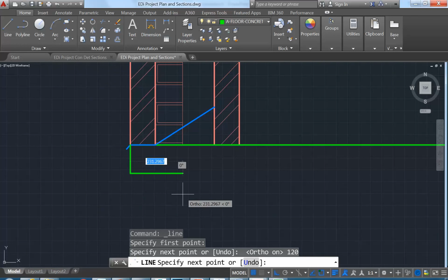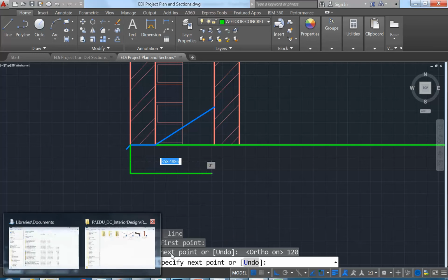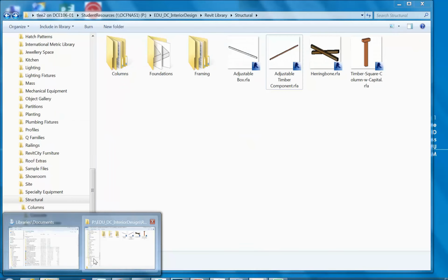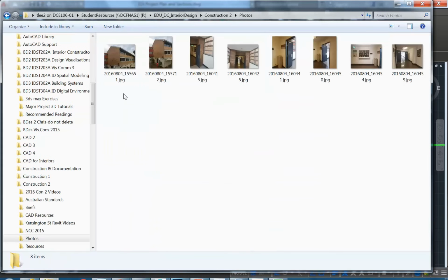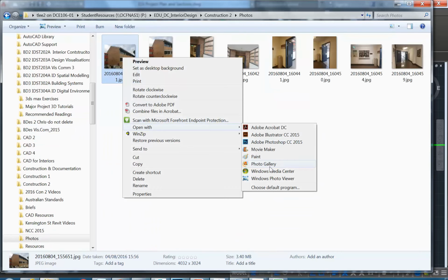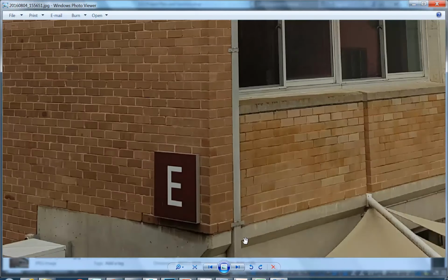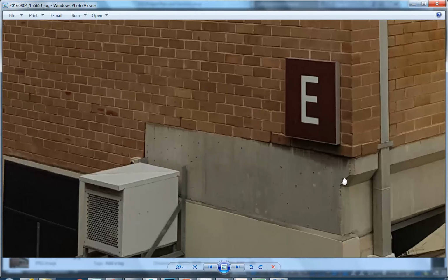It may be slightly different, but it's close to what's really there. And I'll just get some photos so you can see what we're looking at. Okay, so you can see there, projecting across, it's about 1.5 bricks. Or even just visually here, if you compare that distance to here, it's about 1.5 brick courses. So again, around 120.